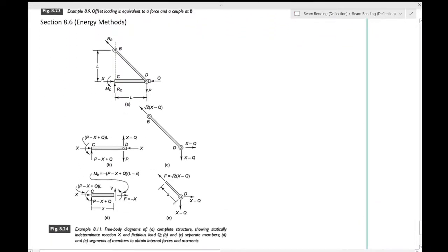And let's now move ahead to the next and the last topic of this particular chapter, which is energy methods. So let's see what it is. In section 2.6, if you recall, you had Castigliano's theorem to find the deflections in simple elastic systems, and to obtain equations for determining statically indeterminate reactions. In this section, we would want to use the same for torsion and bending. We have already developed the energy method for torsion in chapter 6, bending using stresses in chapter 7, and now we want to use that to find the deflection of the beam, using these energy methods.